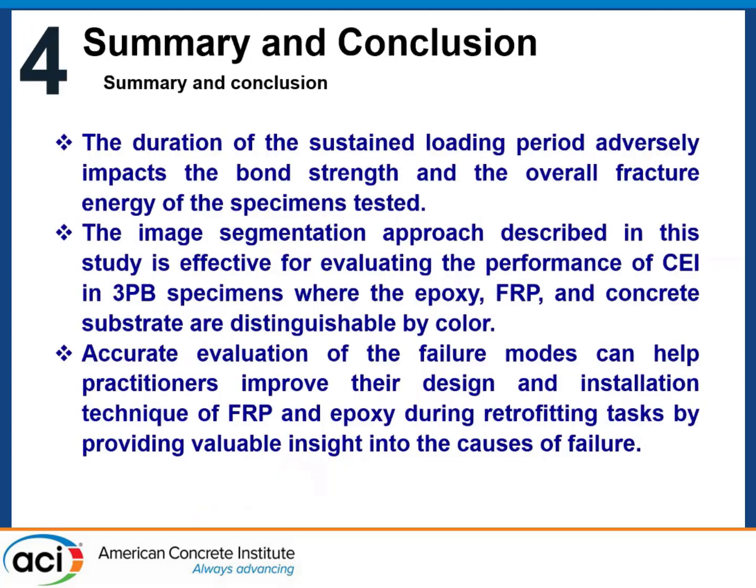These are the conclusions from his testing, and I'm just going to read them in here. The duration of the sustained loading period adversely impacts the bond strength and the overall fracture energy in the specimens that were tested. The image segmentation approach described in the study was effective for evaluating the performance of the concrete epoxy interface in 3-point bending specimens, where the epoxy, the FRP, and the concrete substrate are distinguishable by color.